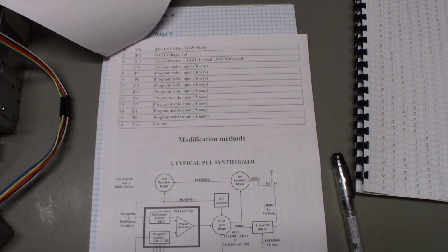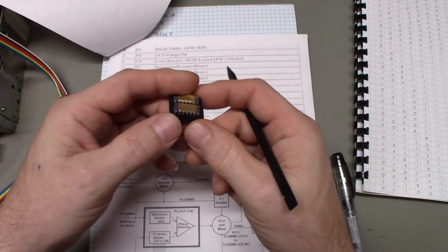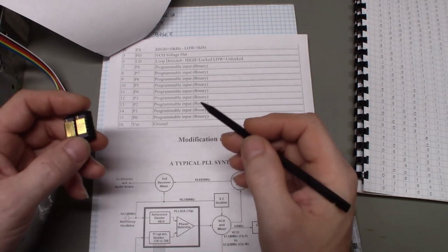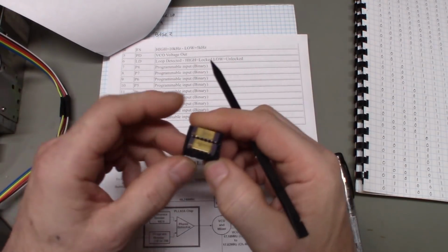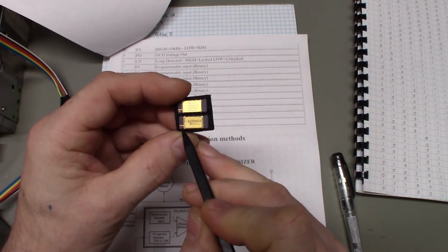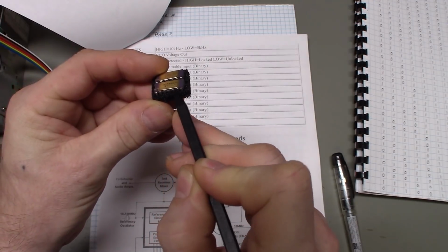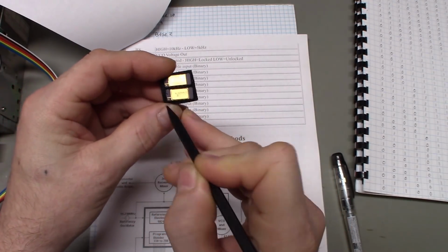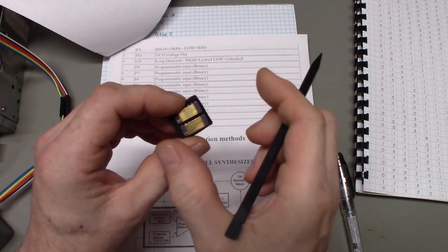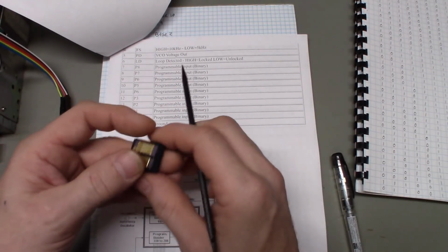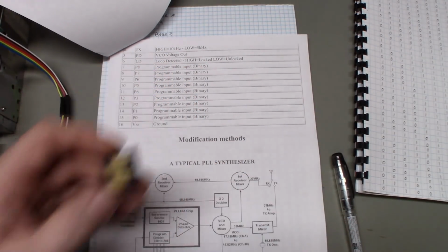When I say pin number, and this is where I say things, there's a lot of things that are backwards. This is the first thing that's backwards. So let me just reach over here and find one. Okay, here's some ICs. These are not PLLs, but when I say pin number, I mean the physical pin on this IC here. There's an identifier that identifies pin number 1, the little dot. So that's pin 1, and then it would count pin 2, 3, 4, 5, 6, 7, 8, 9, 10, 11, 12, 13, 14, 15, 16, on around. It varies how long the IC is, how many pins it has. But that's the physical pin number. So when you hear me say pin number, I mean the actual pin on the IC.